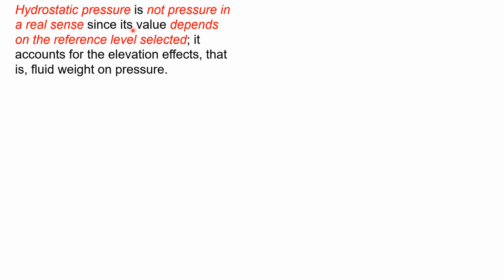Hydrostatic pressure is not pressure in the real sense, since its value depends on the reference level selected. It accounts for the elevation effect, that is, the fluid weight on pressure. Hydrostatic pressure, I think you understood from statics. A different level, a different height from the free surface, gives a different pressure. The deeper you go, the higher the hydrostatic pressure. That's why it depends on the reference level selected.